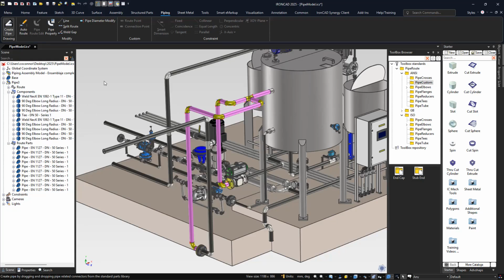So there are some things that we're still improving, especially to support text-based parameters to be used in these components. Those are some things that we'll fix in the official release, but you can get an idea how this is going to work in the pre-release version. All those things will be called out in the bill of material on the drawings. If you use our drawings, we have two types of drawings. One is the ICD, which can be used to create this bill of material. If you use Costa Draft, there's also an option to create the pipe route, which will actually draw the center line for all the pipe run components so that you can dimension that center run, or center points and center lines of these components in the drawing.